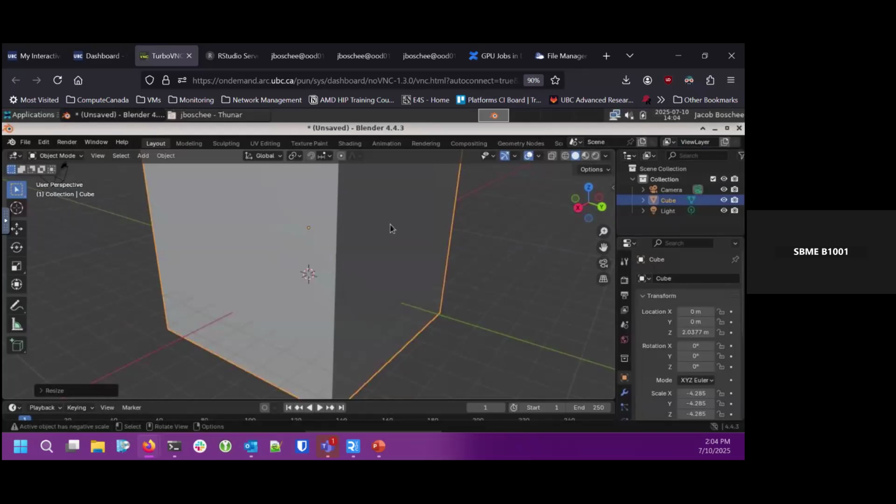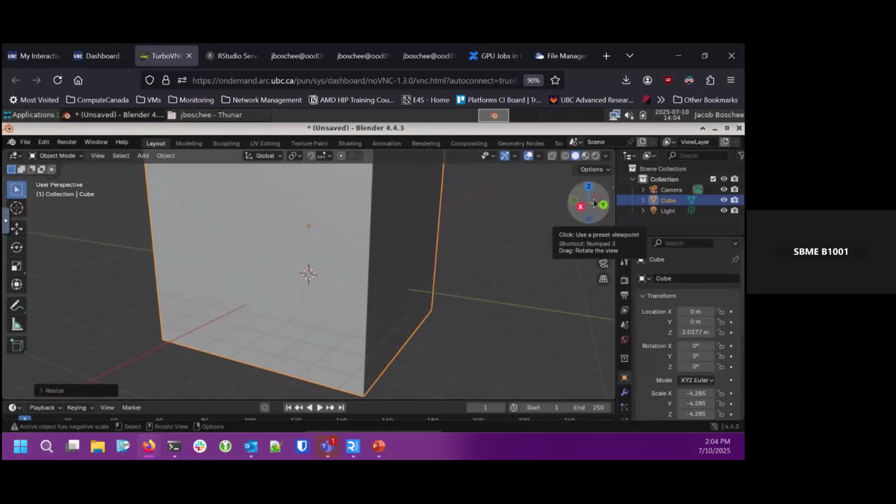So make sure that one, your software handles software accelerated OpenGL, and two, as I found out when I was testing Blender, make sure you give it enough CPUs. I tried running this with 4 and it was very slow. In this case, 16 actually runs pretty well and is pretty smooth. So test out your software if you're doing 3D work and see what sort of specifications might need to be added for it to have a smooth experience.